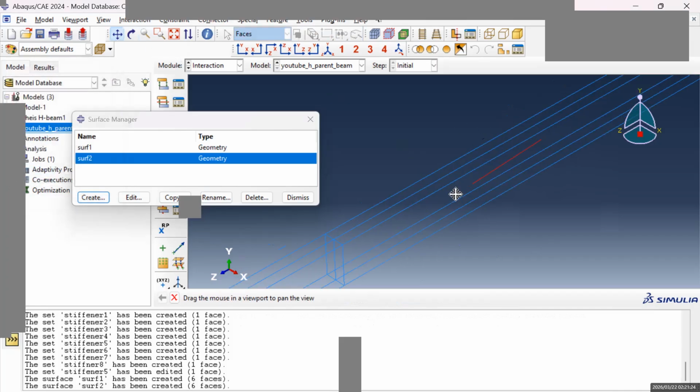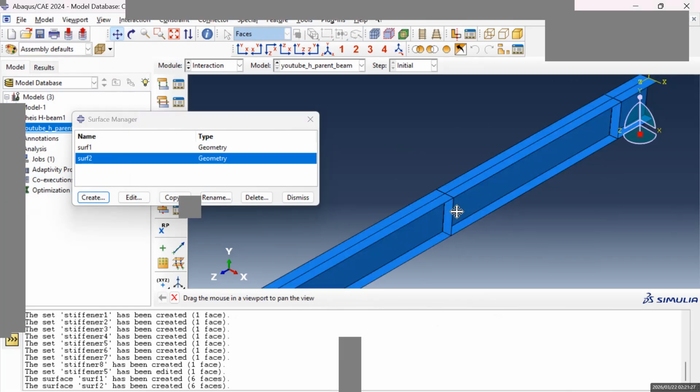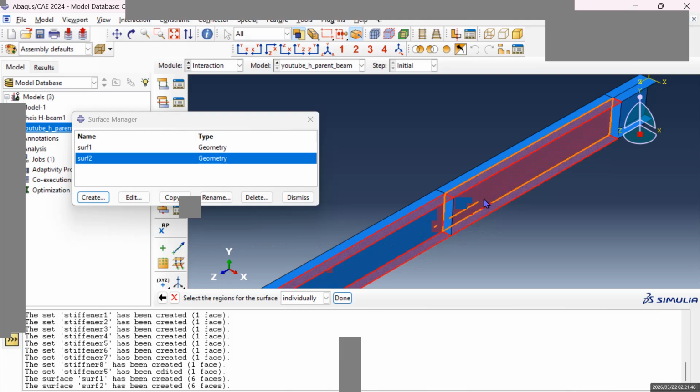Now we are on this side. Stiffener number 3, right? It's connected to this. Okay, so I'll press escape, and then it's connected to this part. Shift this part, this part, this part, this part, and this part. Okay, no mistake, right? Here, if you make a mistake, the computer won't give the result you want. It's gonna be an error. So you have to make sure all of the surfaces have been sealed or welded together.